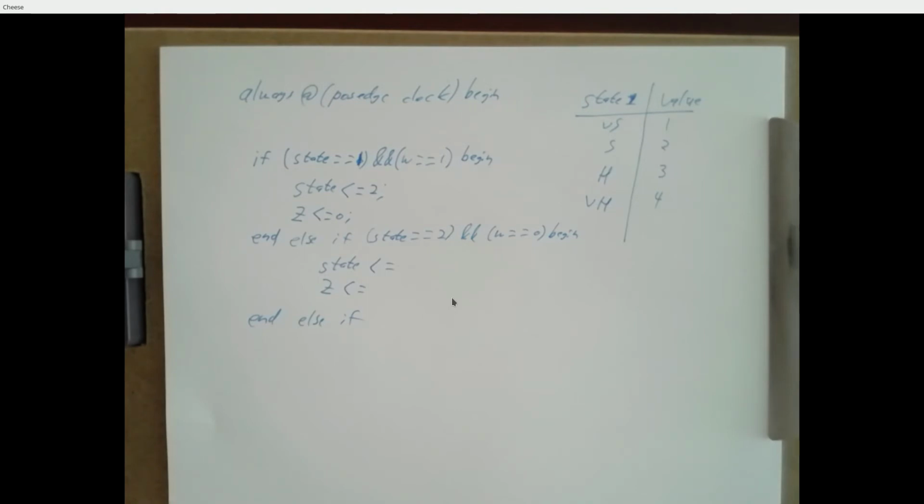But this gets you more comfortable with putting things in the module inside the always block that change the behavior of the system. And then maybe don't do the mood machine. Maybe design yourself a simpler machine with like 2 or 3 states and make a state diagram and see if you can write Verilog to make it happen. And then go ahead and do the mood machine.